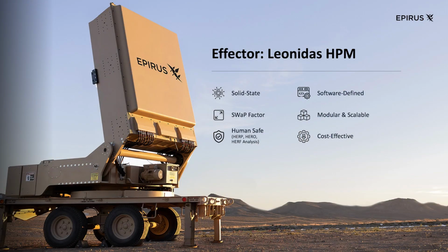And this specific system has utilized high power gallium nitride transistors. Our original founders came up with a board called Smart Power, and that very uniquely biases our GaN transistors in this system. That makes them very efficient and a lot easier to control. So our entire system is software designed. We write all the software, and my team, the RF team, designs all of the RF amplifiers that go into this chain. Like I was telling someone right before this talk, we have about 6 stages of amplification. That is a lot of GaN transistors. These transistors are also scalable into any kind of array. So this is our largest system, but I will show you a smaller one.